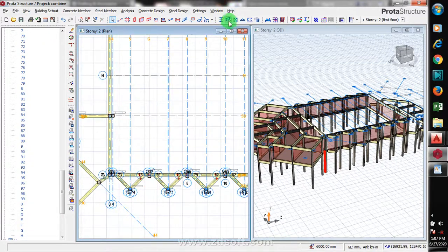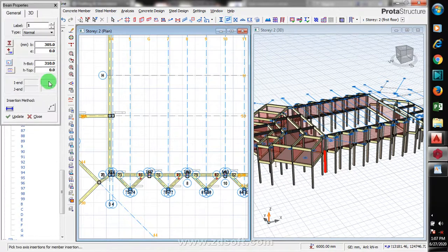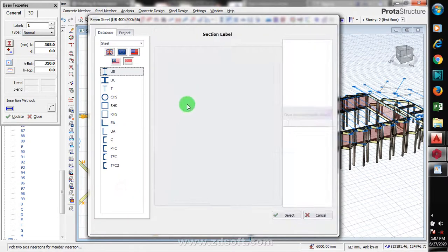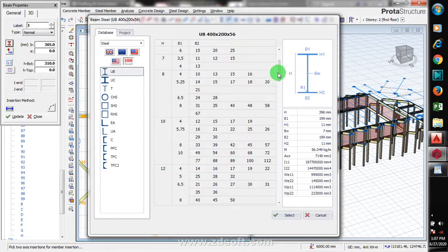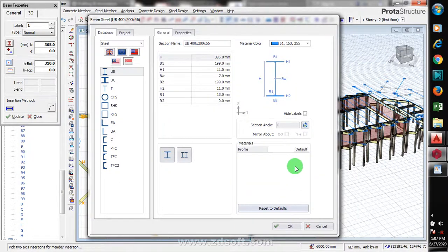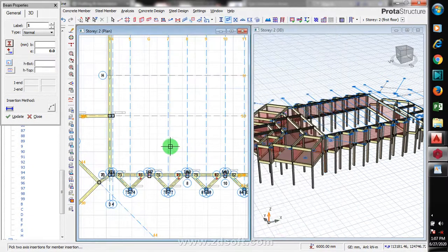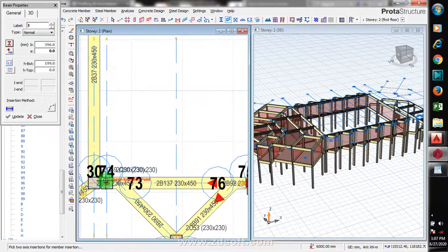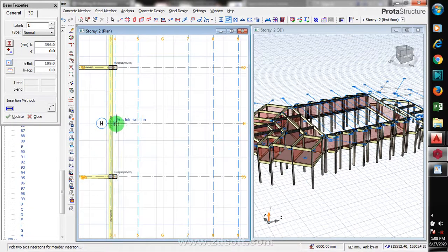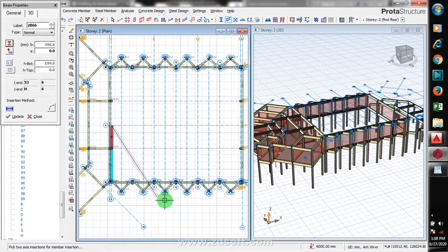All I have to do now is just to draw my steel beam, go back to that, I can pick a section, I click here, I will take this down. Now when selecting a section, make sure that here on this video I'm only going to be picking randomly, but make sure that your design is not just safe but as well economical. Okay, it has to be safe, it has to be economical.